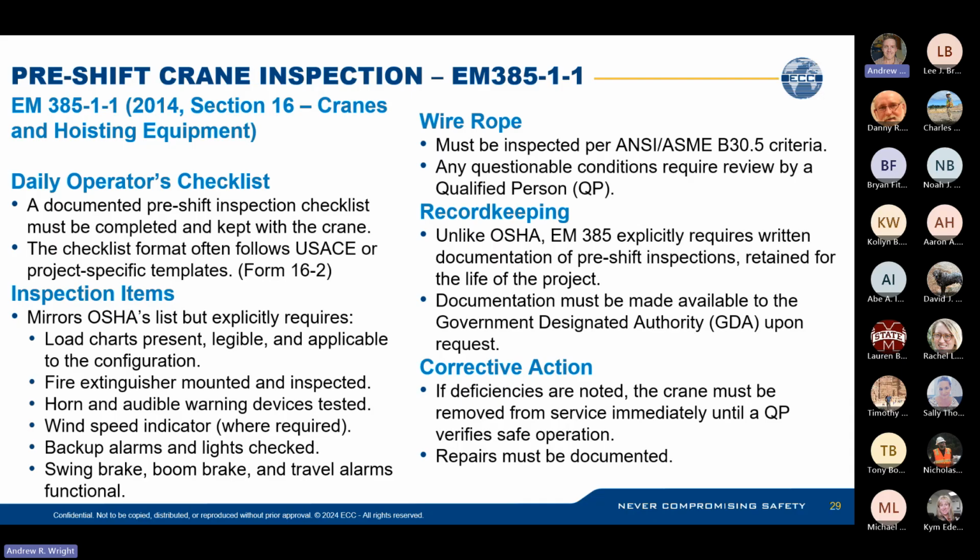So pre-shift inspection per EM 385, it mirrors a lot of the items for the OSHA inspections. There's a standard pre-lift checklist that is required on U.S. Army Corps jobs that are governed by the EM 385. That's the Form 16-2 standard pre-lift checklist that should be completed daily by the operator.